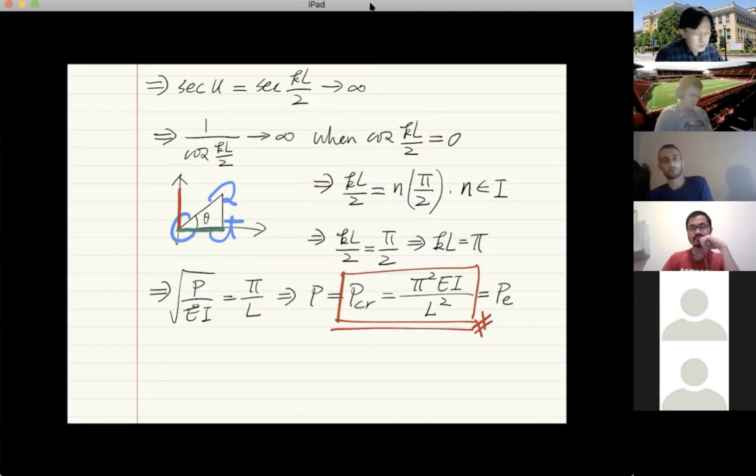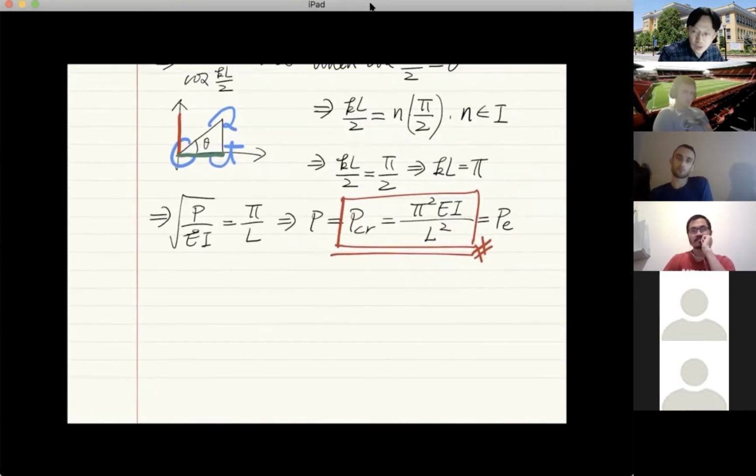Many of you must feel totally not surprised because you already know what the answer should be. Why? Because we talked about this before. We said that the buckling of beam columns depends not only on the lateral loading, but also on the boundary condition. If we have a simply supported beam or even the beam column, the buckling load must be PE. That must be it. Okay.